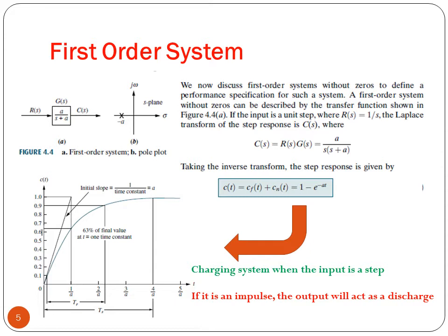And if it's not stable, it doesn't make sense to study the response of this system. Thus, in order to make sure that the system is stable, we have to verify that the closed loop poles have negative real values. They can be complex, but in fact the real part must be negative.